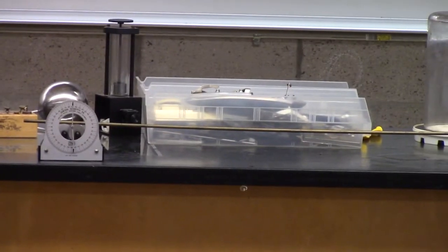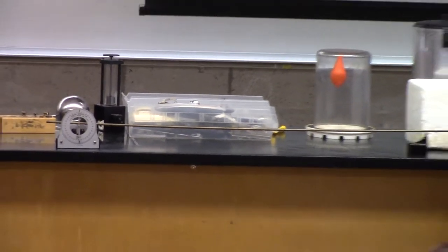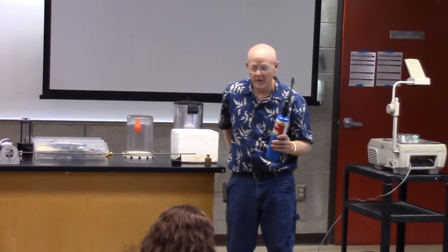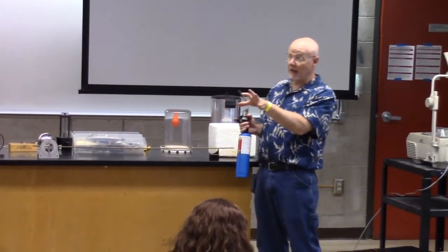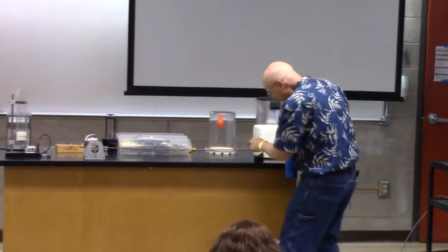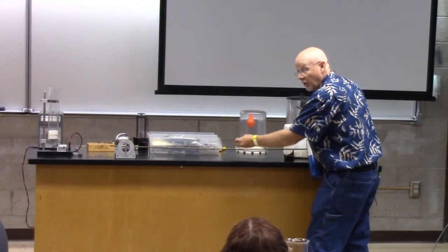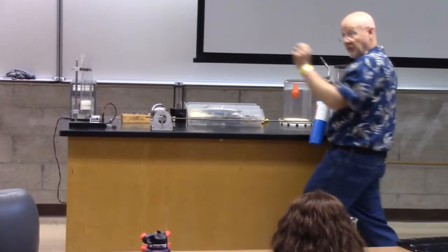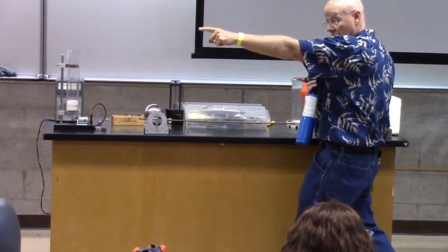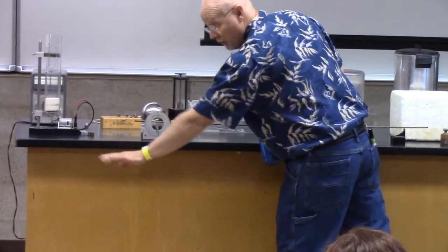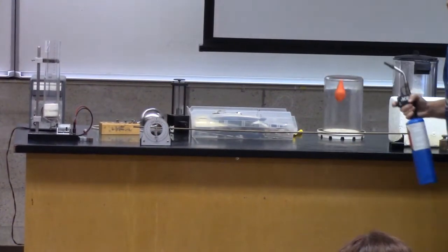And as a quick experiment to show thermal expansion, I'll start with the needle pointing straight up and say, well, what would happen if I warmed up the brass rod? And I claim, because of this thing called thermal expansion, that the atoms in here are going to hit each other harder and this rod's going to grow. It's going to expand over towards the far side of the room, which according to this needle then should move in a counterclockwise direction.